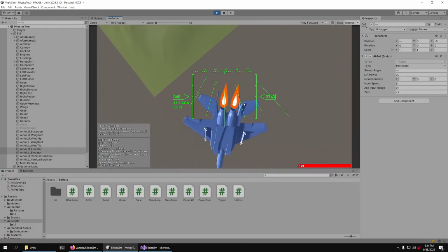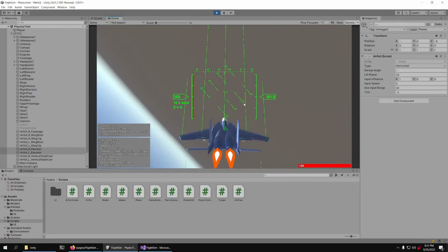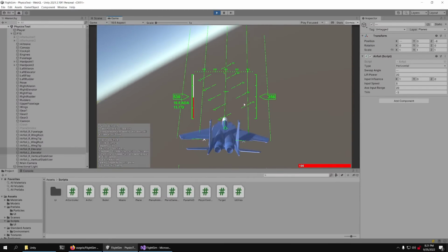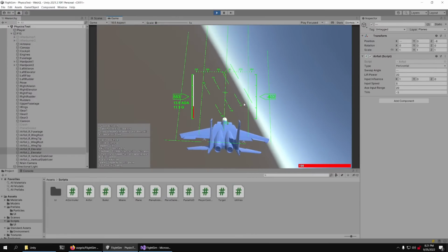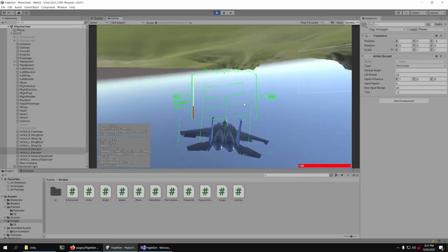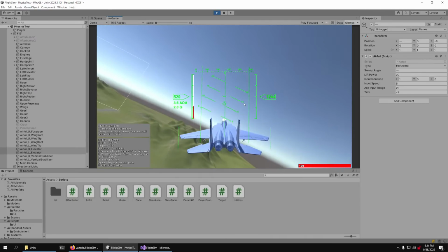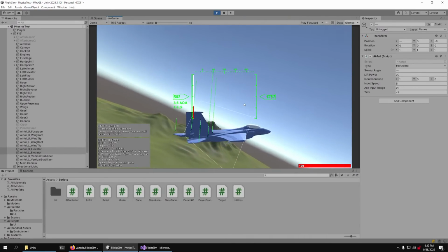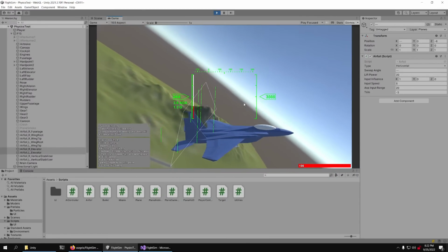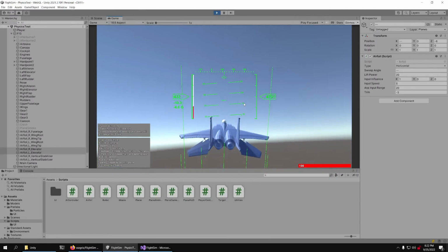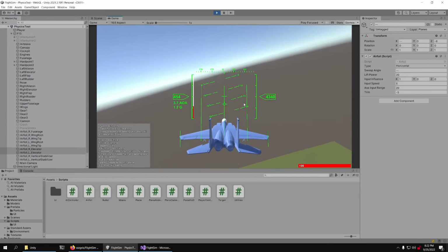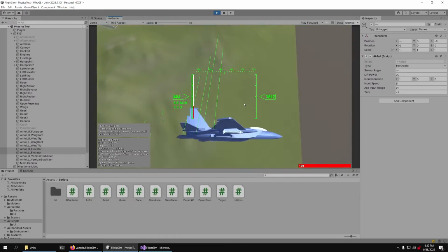That is something real planes have to deal with: setting the trim as you go through different phases of flight. When I play simulators, I find that really tedious, and I just don't want to do that in a game. But it appears that with this physics-based code, you do now have to actually worry about trim settings. And we're actually seeing some dynamics here. The trim is pitching me slightly upwards even though I'm not giving input, because I was going at a different airspeed, so you need to change trim as you go through different airspeeds. That's the general gist of it.